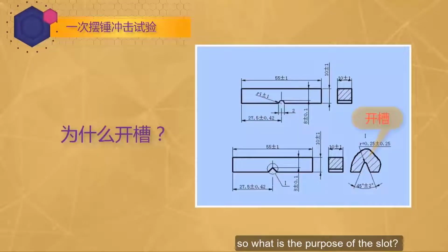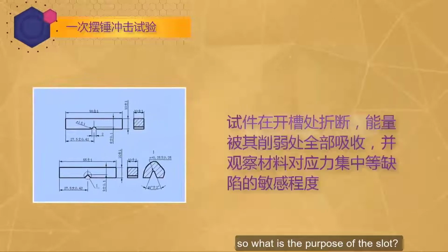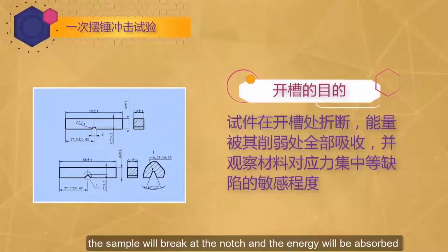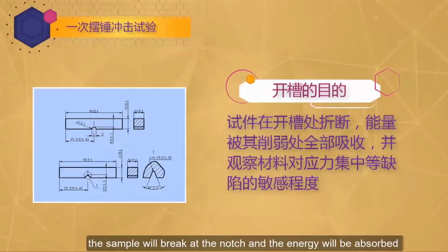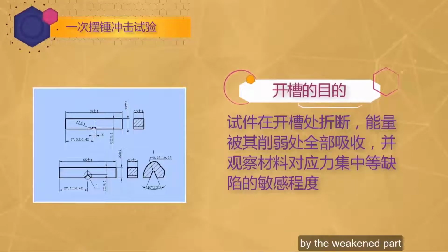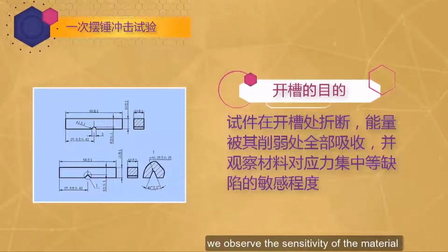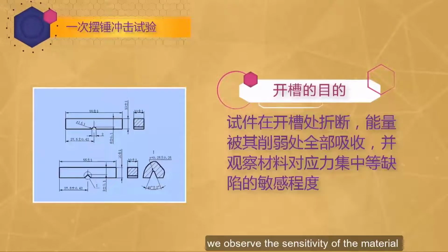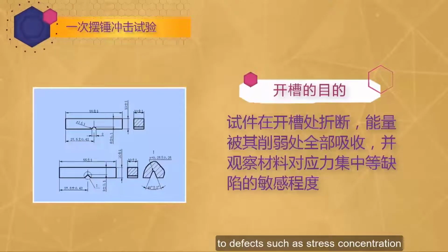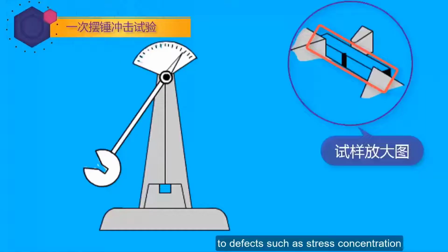So what is the purpose of the slot? During the test, the sample will break at the notch and the energy will be absorbed by the weakened part. At this time, we observe the sensitivity of the material to defects such as stress concentration.